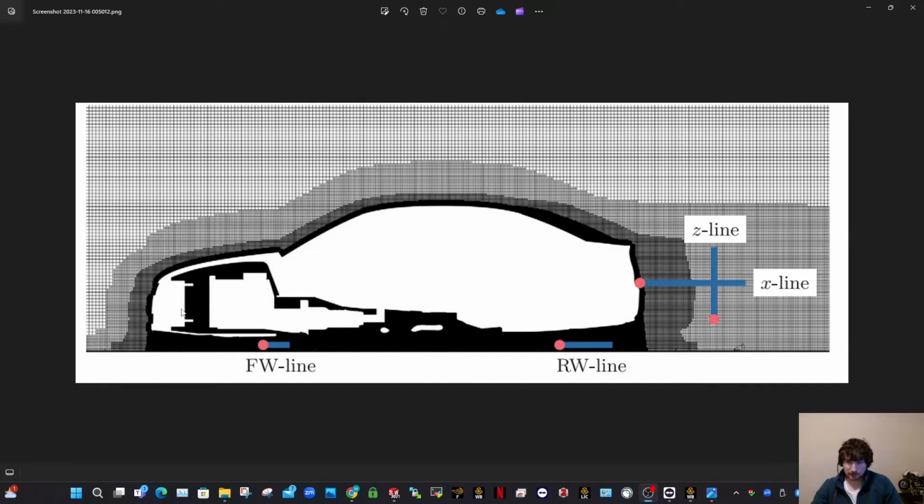And the boxes are fine as well. There's nothing wrong with the boxes. They're just not as cell efficient, there's probably extra cells there that don't need to be there. And this as well, see the wake has to be made so that you're able to resolve that. That could have maybe even been a bit longer. Grand. Okay, so we'll go back to SpaceClaim.